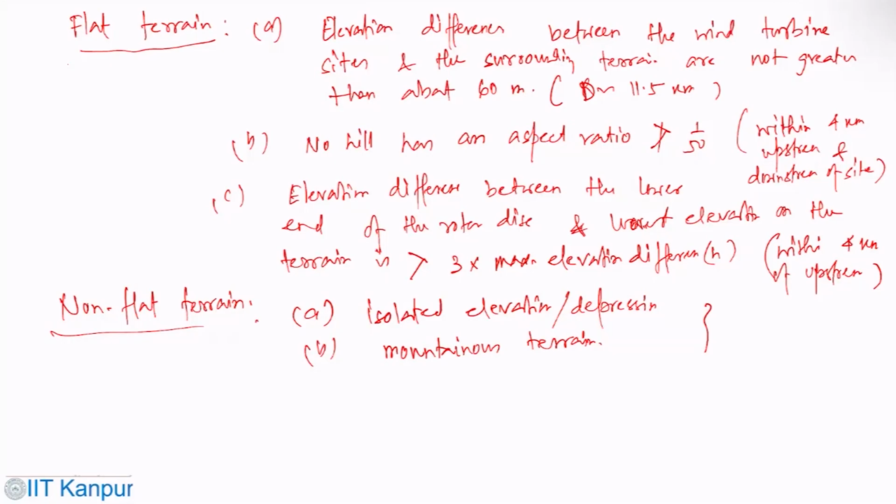For example, if an isolated terrain which is 200-meter high and 1,000-meter wide is situated 1 kilometer south of the proposed site, then the site could be classified as non-flat. If, however, the wind blows only 5% of the time from this direction with a low average speed, say 2 meters per second, then this terrain should be classified as a flat terrain.